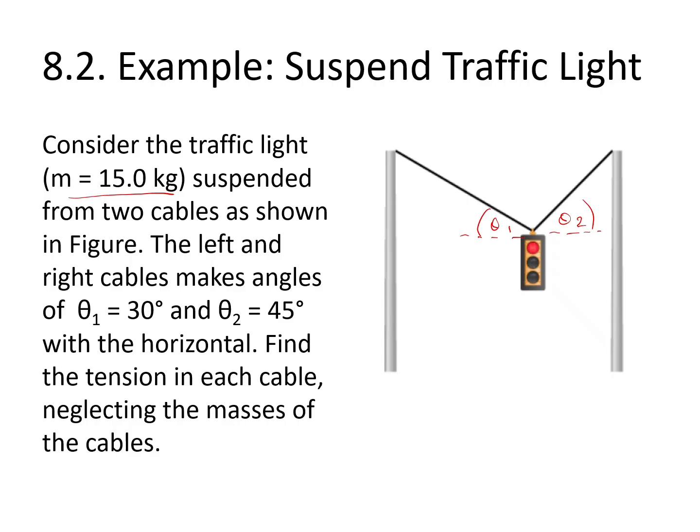The two cables' tensions do not have to be equal because the cable angles are different. This is an important prediction. Since the right cable is at a steeper angle, it has a larger vertical component for the same amount of tension. The calculation will show exactly how the two tensions compare.